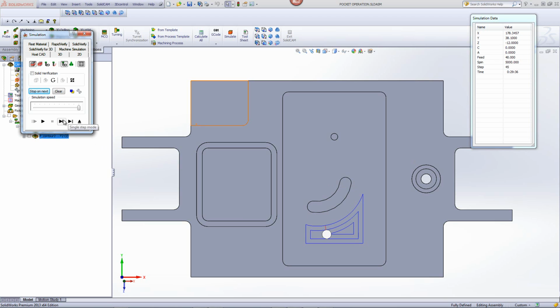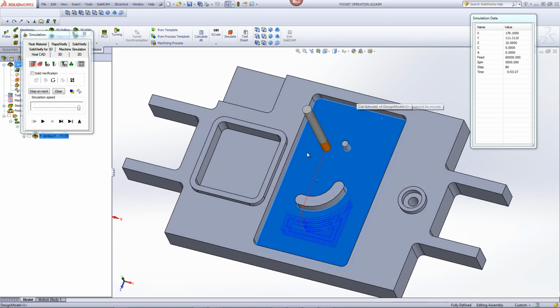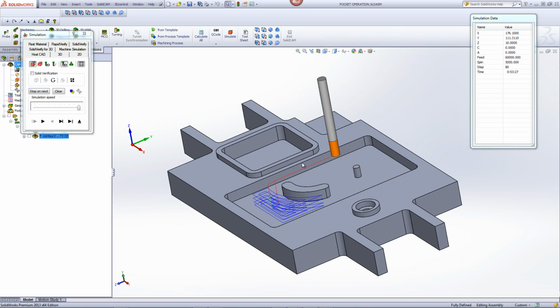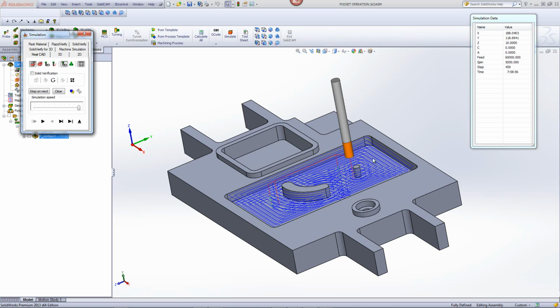And then when it finishes the total depth of that pocket, it'll then go up in the air. If we take a look at the side view, instead of going through the material itself, this way allows it to move very quickly above the material itself and also not wasting any time cutting material where the tool will be passing through at the end in any case. It'll then re-enter the material itself, work in those areas, and the same thing in that area as well.